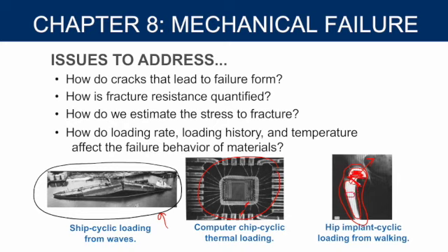This is the smallest cross-sectional area. The force being applied by the body is going to be the same throughout the material. Divided by the smaller area, you have a higher stress at the neck. And just from the loading over and over again, there are probably some voids in the material that compromise the cross-sectional area and cause the material to fail prematurely.